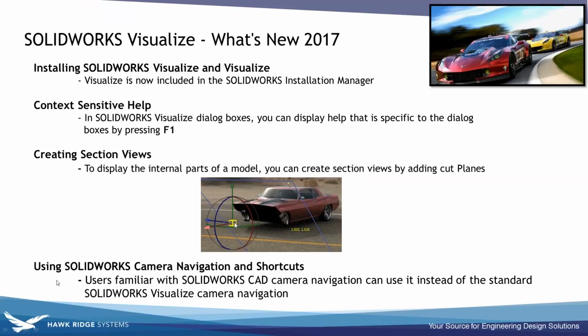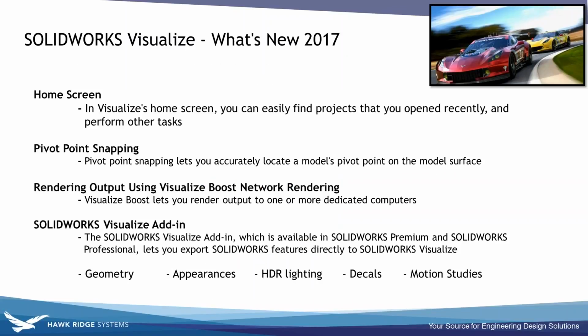But using SolidWorks camera navigation and shortcuts. So if you're familiar with SolidWorks and you go to Visualize, all the navigation and stuff is different in Visualize than it was in SolidWorks. So now you have the option of setting them the same. So when you're working in SolidWorks, you go to Visualize, everything operates very similarly. So that's really nice.